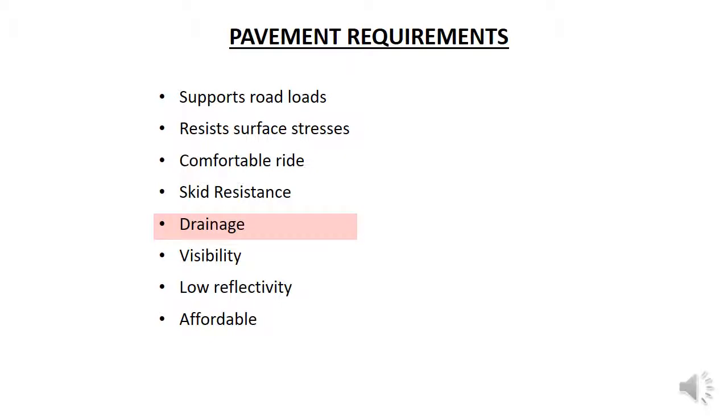Water on the road can result in less contact between the vehicle tires and the road itself, which can result in vehicles losing control or hydroplaning. Additionally, ponded water on the surface can significantly slow vehicles and may result in the driver losing control. This is especially a problem when depressions form on the road and the ponded water is deeper.